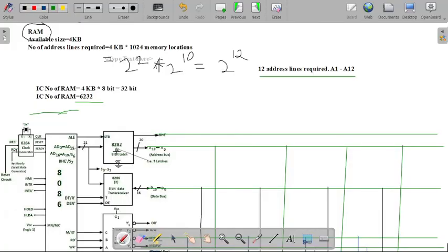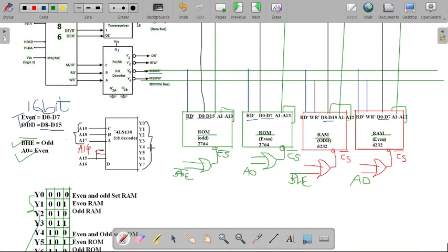So here you can consider that in the 74LS138 3-to-8 decoder, we have these three input lines. So the remaining three address lines, that is A19, A18, A17, we are considering for A, B, C input. And these Y0 to Y7 are the 8 output lines in our example.